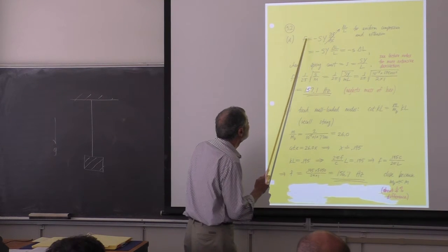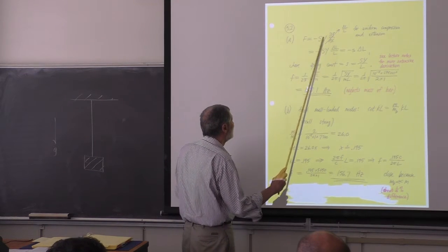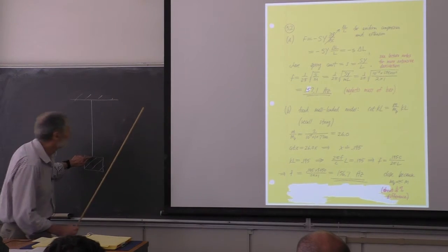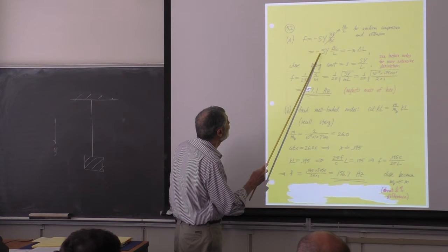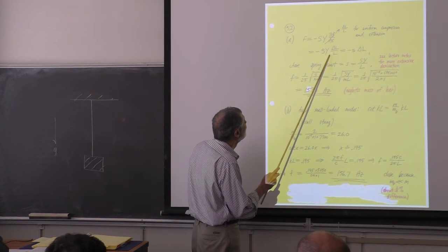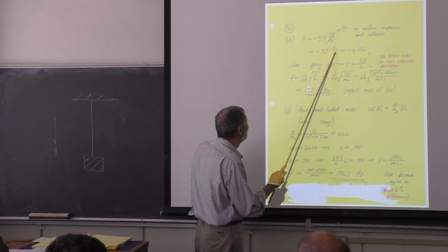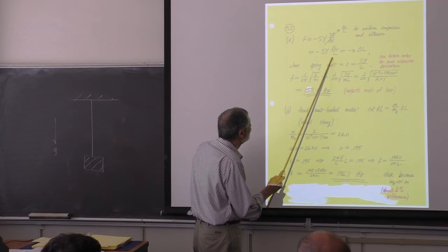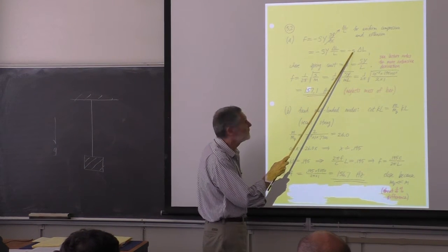And this is our formula. Remember, this is the basic formula for the force of one part of the bar on the other. I'm going to evaluate it by looking at the end down here. And I get this expression. And you can see that we can put this into Hooke's law. Well, it's very easy. We just recognize that these numbers right here combine to give the spring constant, little s.